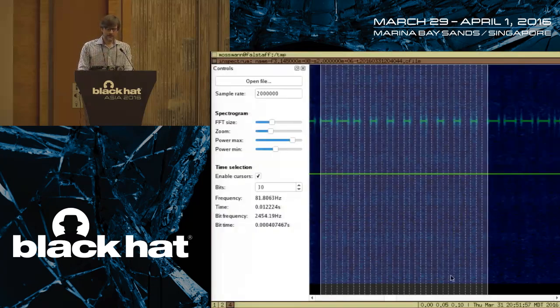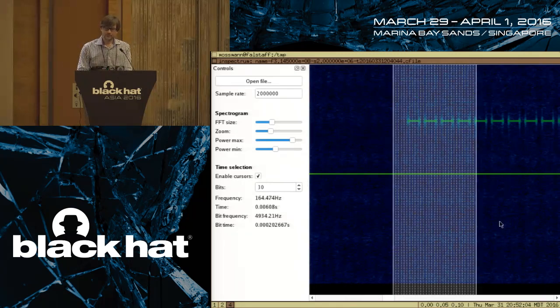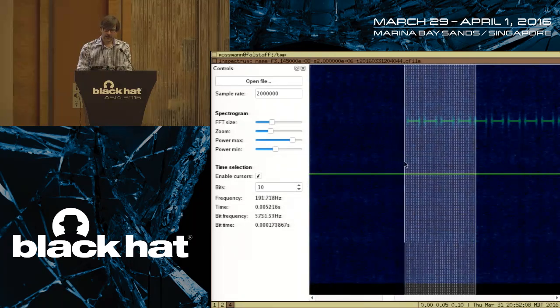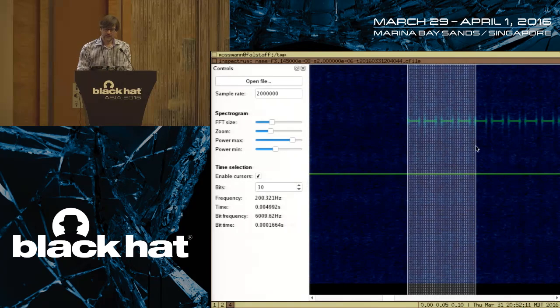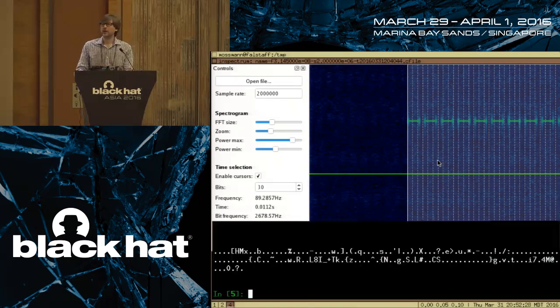If we look back in Spectrum, at the beginning of a packet, what we had was not 1, 0, 1, 0, 1, 0. What we have is, in fact, well, I don't have this quite set up right, but what we have is 1, 1, 0, 1, 1, 0, 1, 1, 0. We have a waltz instead of a two-step. And that is not going to satisfy the Yardstick 1's notion of what a preamble looks like.